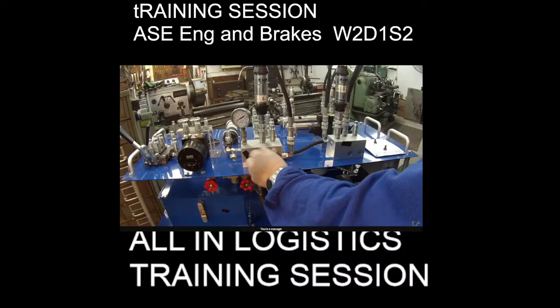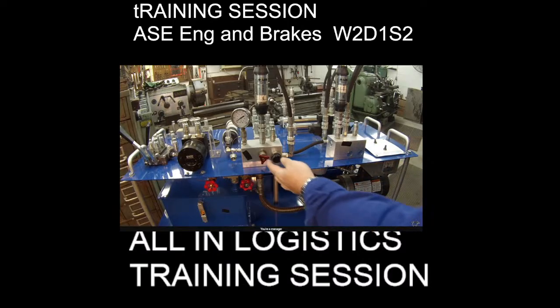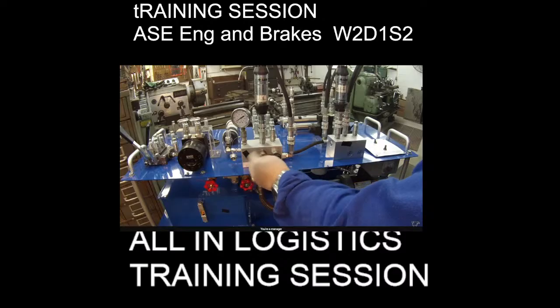So the only thing you see right here on the gauge is about 10 psi. The reason you see that 10 psi is because it's taking that amount of back pressure to push that fluid through these fittings and through this block right here and make it go back through this filter into the tank, as a resistance. So I'm going to shut this and make the resistance come back, and you'll see that pressure go back up.